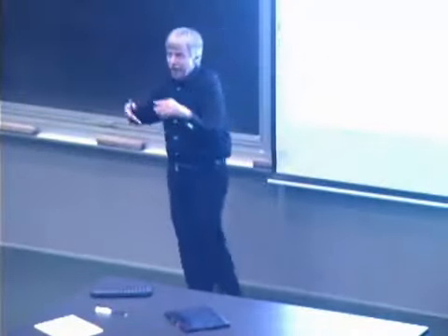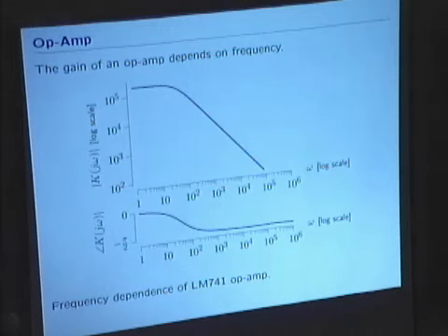Similarly, the phase changes. The phase at very low frequencies is near 0. That's kind of ideal. 0 would mean in phase. The output reliably tells you what the input is doing. So that's good. But as you go to higher frequencies, you start to pick up a phase delay, which means the output's telling you what the input did a little while ago. Okay, that's less good. So the performance in terms of providing a lot of gain is quite good for some frequencies, but not for others.